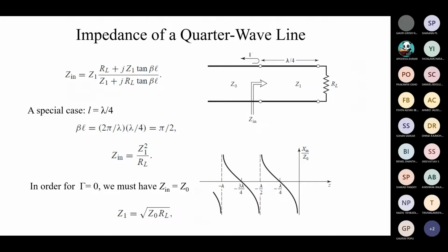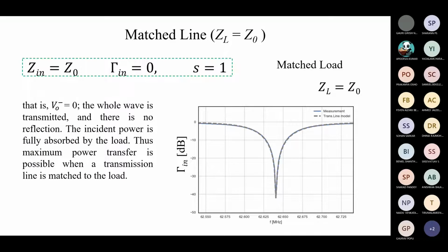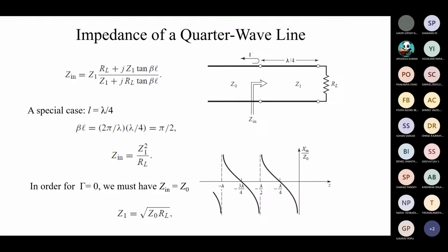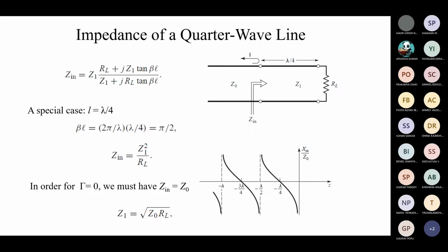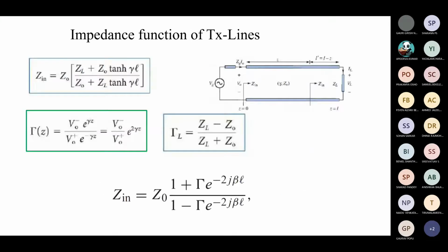And the advantage of studying this is that we can construct so many circuits using the transmission line itself, particularly matching and then creating reactance at a particular wanted place, or in order to stop a particular signal we can create reactance to cancel that signal. All these things can be done within the scope of transmission line. That is why most of the high frequency systems are developed using transmission lines itself.